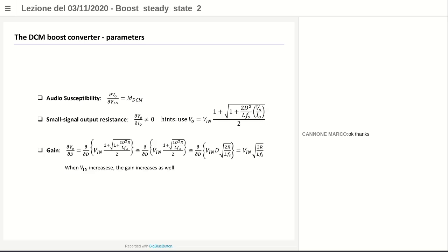The peak-to-peak current and the RMS current are larger. That means you have to buy specific components that withstand larger RMS and peak values. Typically these are more expensive, bigger, etc.